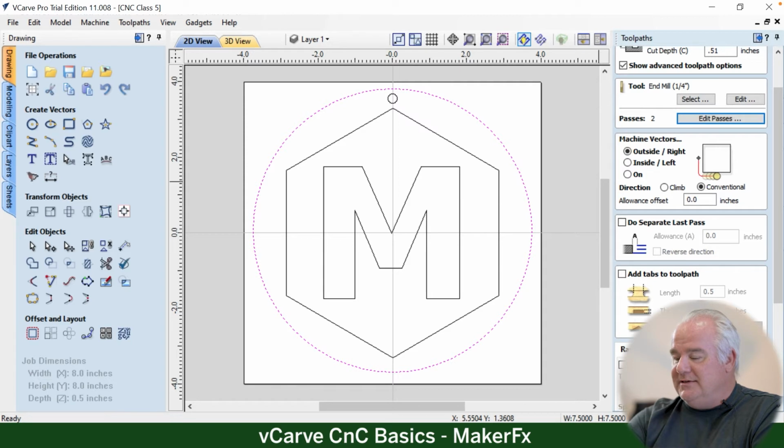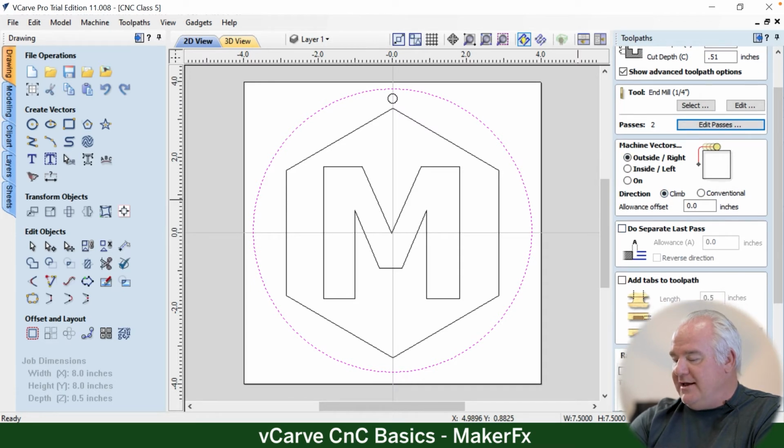So it's something for you to think about relative to the material you have and following the grain in the case of wood. At some point in cutting this, if we were cutting oak, it's going to be going with the grain, against the grain, and cross grain. So you may find that the piece of material you're using has a different quality with a different setting of this. We're going to come back and do tabs.